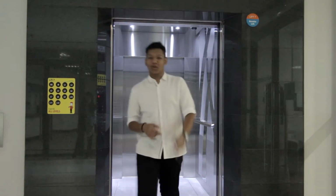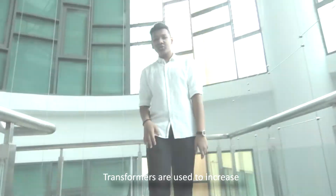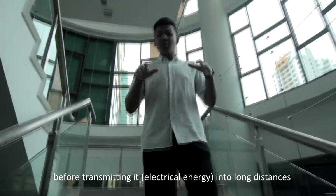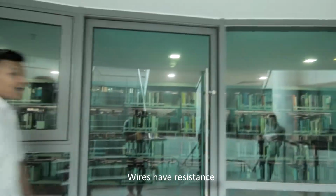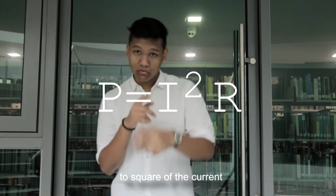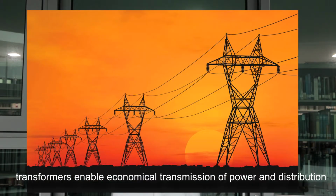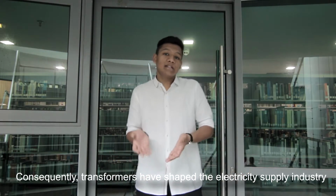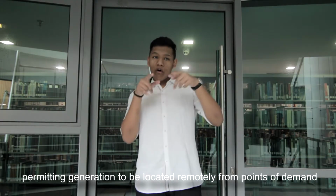Hey guys, today I'll be talking about applications of transformers. Kapow! Transformers are used to increase or step up voltage before transmitting it over long distances through wires. Well guys, wires have resistance, which loses energy through Joule heating at a rate corresponding to the square of the current. By transforming power to a higher voltage, transformers enable economical transmission of power. Consequently, transformers have shaped the electricity supply industry, permitting generators to be located remotely from points of demand.